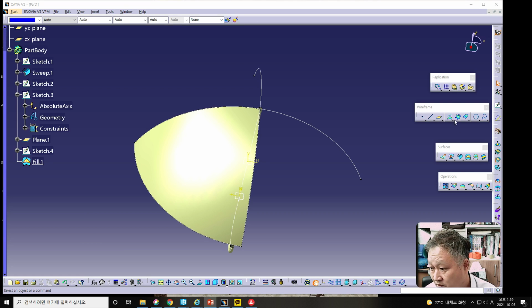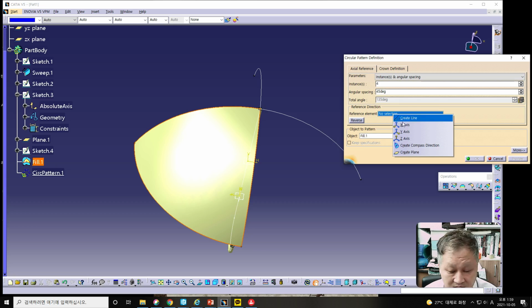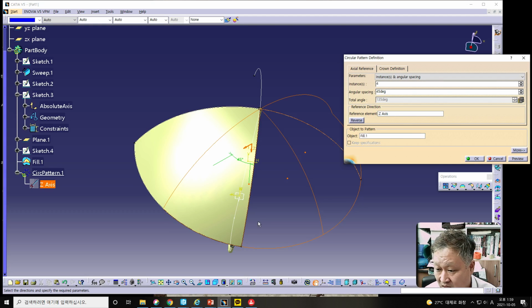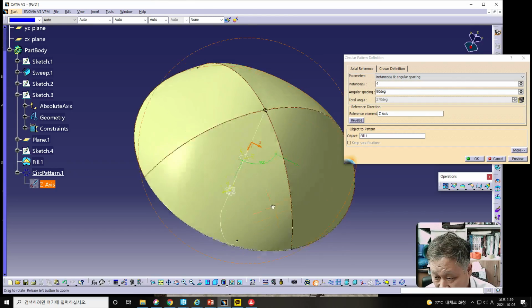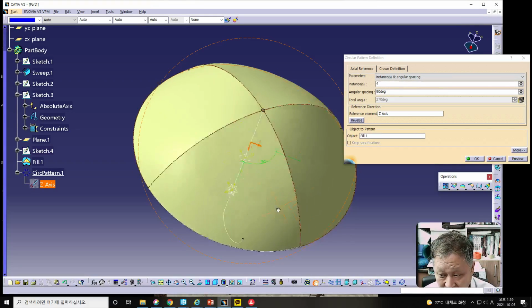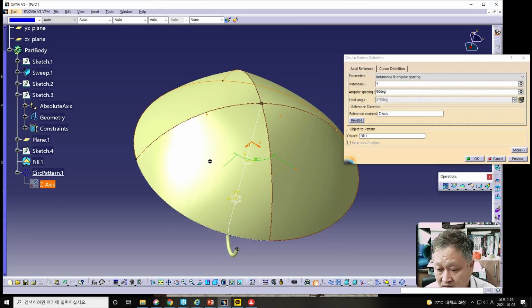And next one we should do by using circular pattern of this button. If you click circular pattern and click this surface, please give it 4 instances in this, and the axis element should be z axis, and the degree should be 90 maybe, because a 90 degree operation is needed. And by using this, we can do another one to this one and this one.